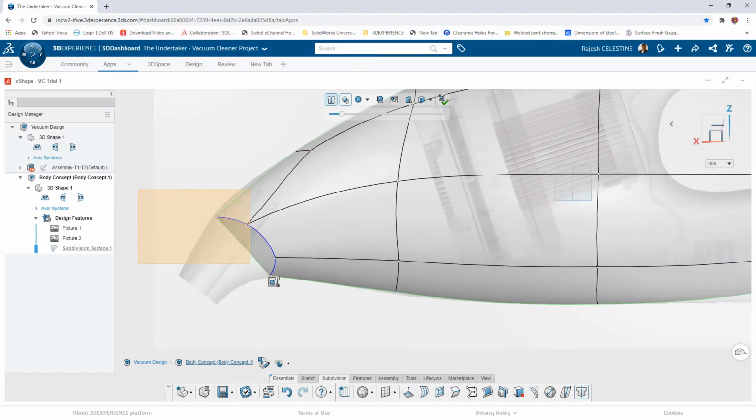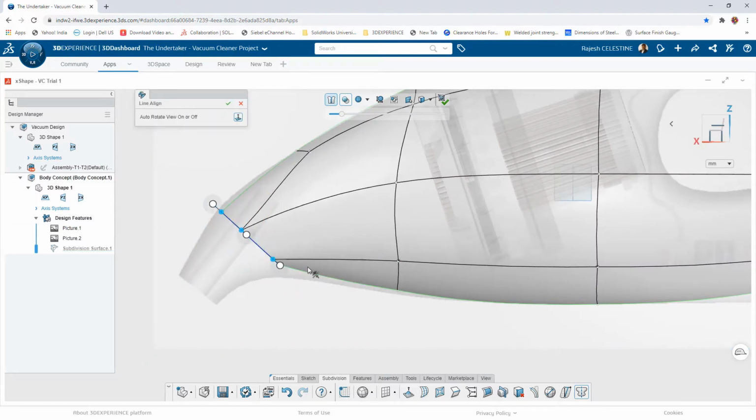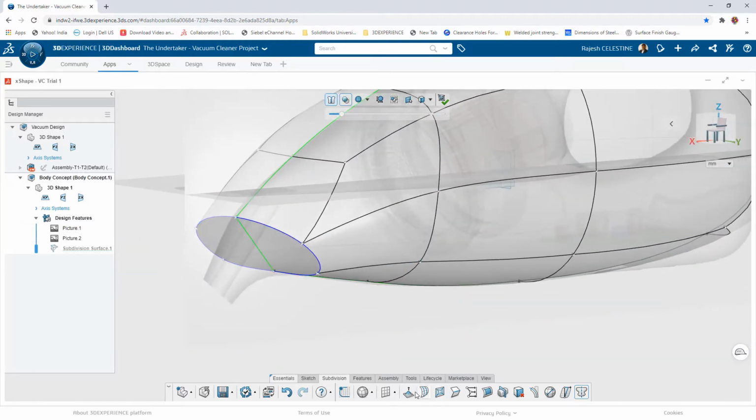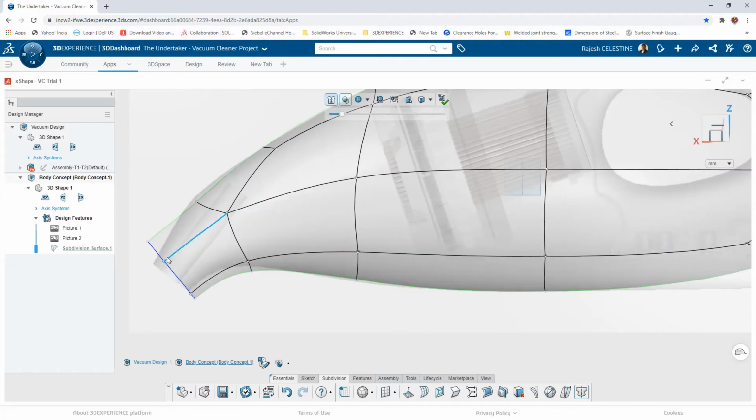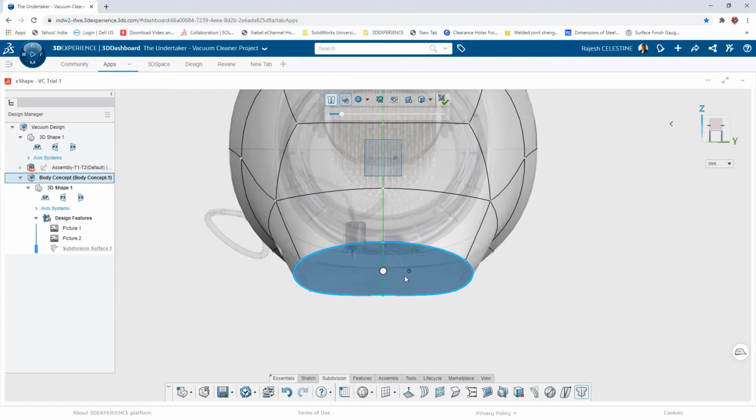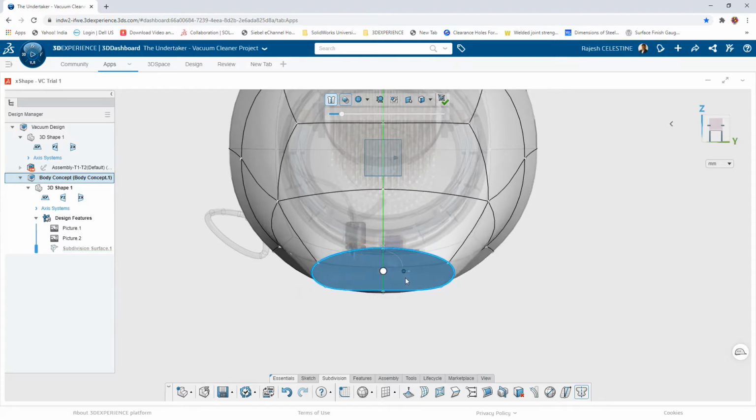The crease feature aids in creating sharp edges, where the percentage of the sharpness can be adjusted. By selecting a group of vertices, you can choose specific tools suggested by xShape to be applied on your selections. After completing your geometry, now you could refine the existing vertices to suit the shape visually.